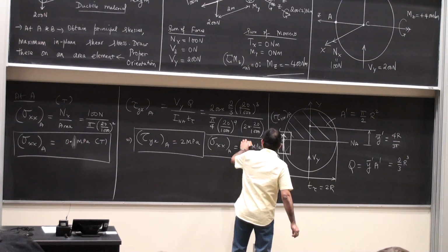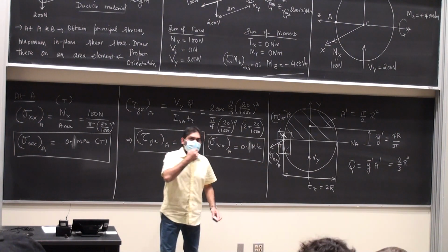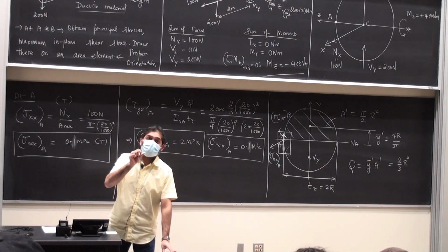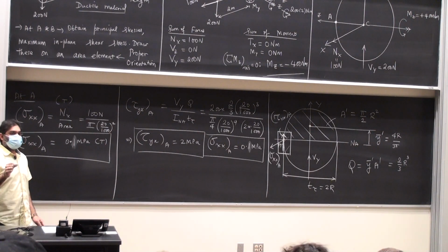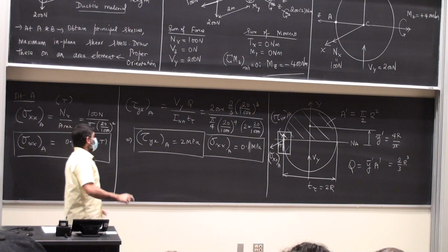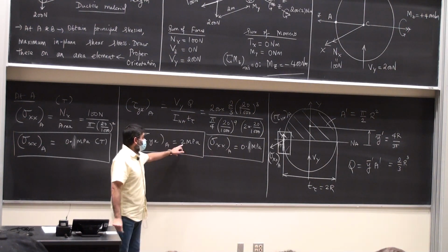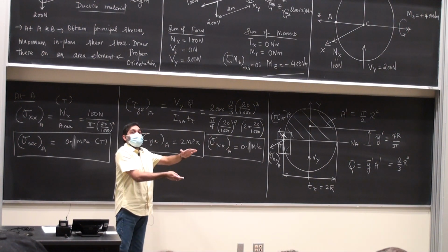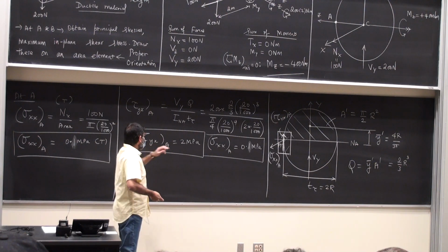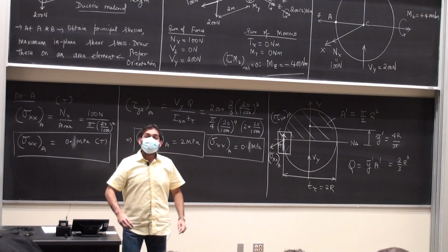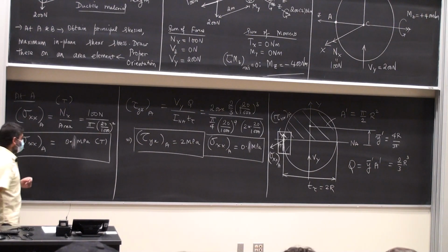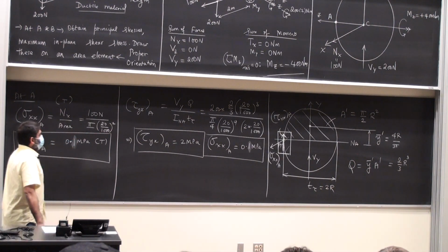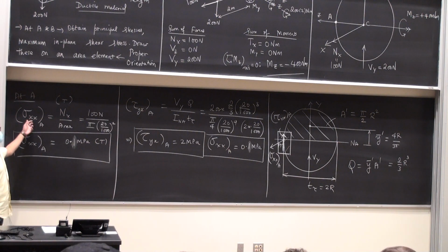You had one job. And as you will see, these values are very insignificant. The major danger to any body is bending stress. This is just going to be a minuscule number. For all that hard work calculating y bar prime, q prime and all those things, this is going to be pretty small compared to your bending stress values. The major culprit always is bending. Okay? Okay, I'm going to clear up this panel here.